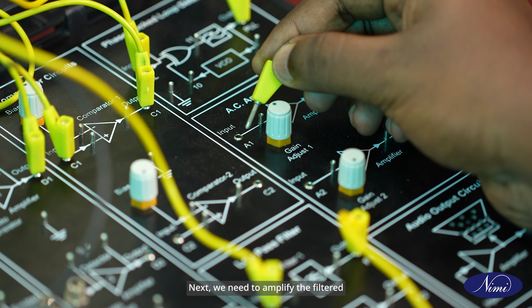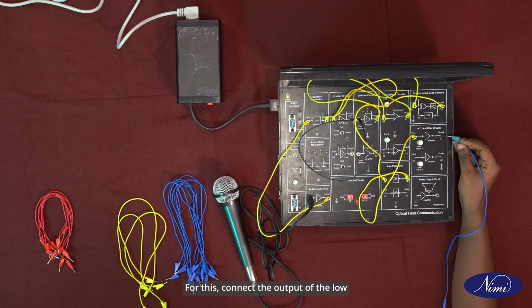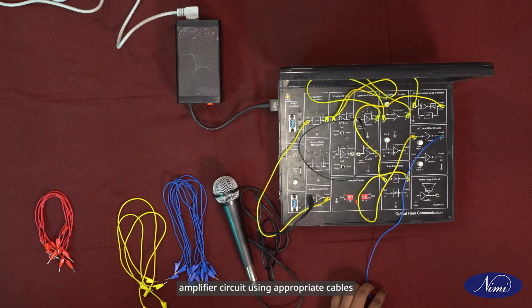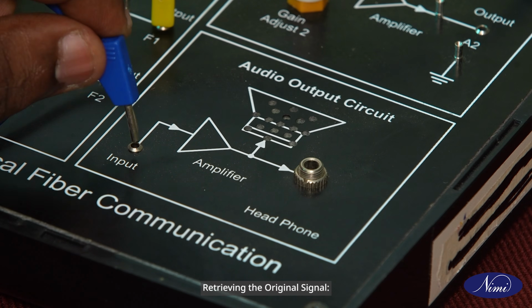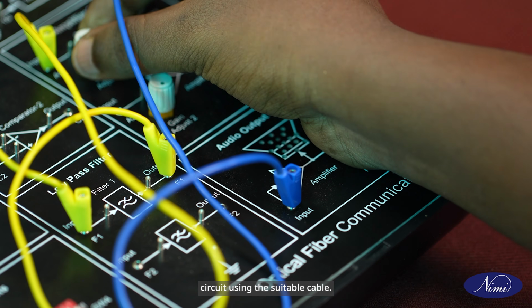Next, we need to amplify the filtered signal to achieve a suitable amplitude for observation. For this, connect the output of the low-pass filter circuit to the input of the amplifier circuit using appropriate cables or connectors. Retrieving the original signal. Now connect the output of the amplifier circuit to the input of the audio output circuit using suitable cable.